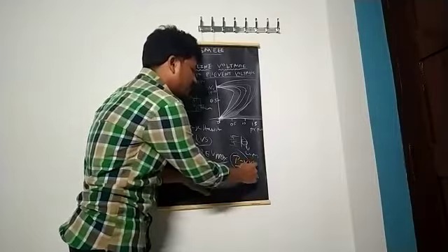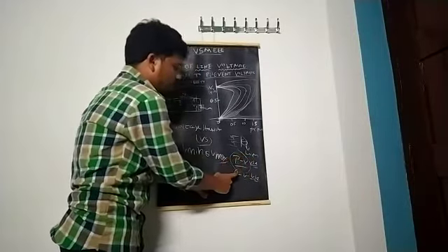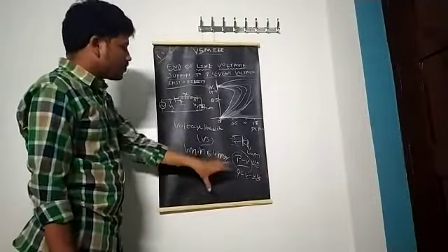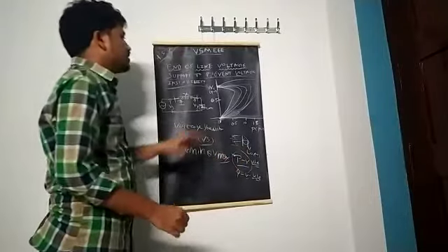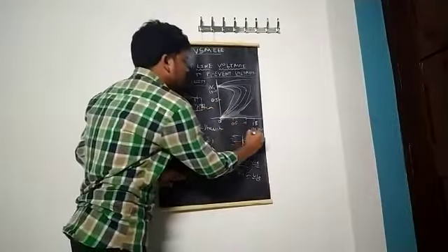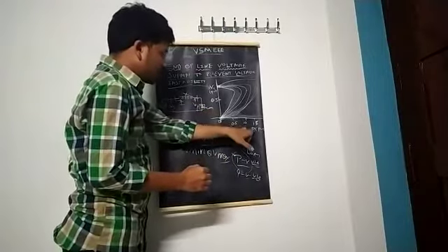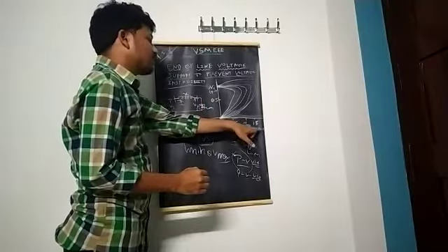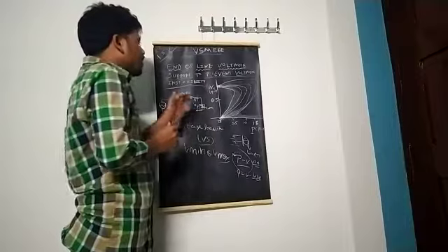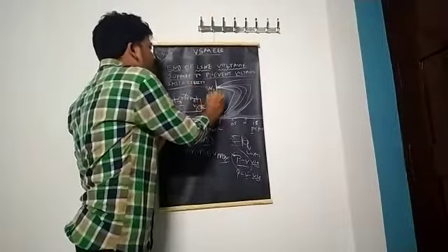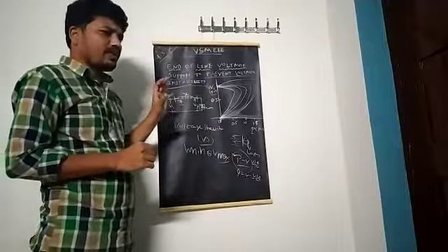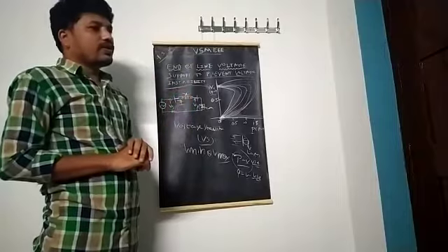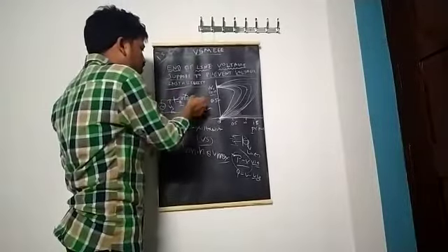Here VSA is voltage stability analysis, V is voltage, P is active power, and Q is reactive power. Generally out of these we go for the PV method to analyze V versus P. Here P is the load power, that is, the power carried by the impedance in per unit value, and VR is the voltage at the receiving end, also in per unit. Generally in the power system, many times the consumer side, the receiving end, faces voltage stability issues. That's why we always concentrate on the receiving end only.